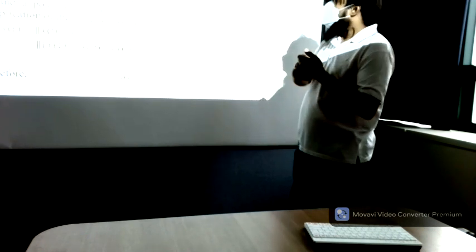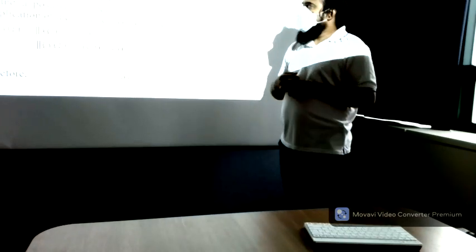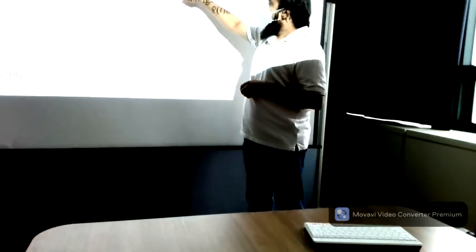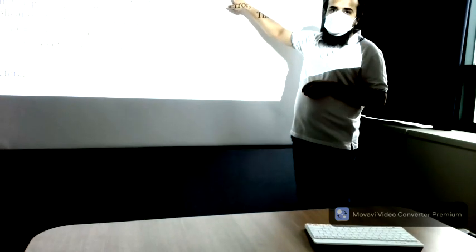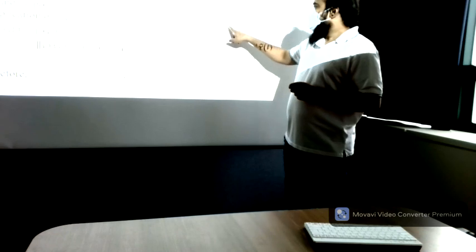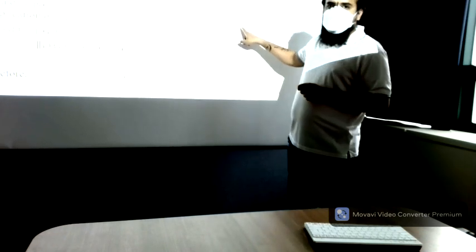Now we set some error bound. We have a bound on the estimated guidance error, that is, we have found a positive number epsilon g such that the estimated guidance error is less than or equal to epsilon g. Okay? And also assume that we have a bound on the navigation error, that is, we have a positive number epsilon n such that the navigation error is less than or equal to epsilon n.